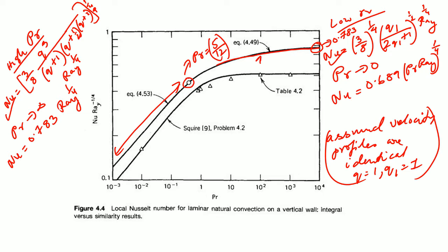Now, in this particular case, you can see that the Nusselt number to a certain extent depends on the analytical forms of the velocity and the temperature expressions, that there is some dependence. But when we choose a velocity profile or a temperature profile, there is always that trade off, and we will see how much that trade off is when we do our similarity solutions, because our similarity solutions will give you that kind of a profile. So, the similarity solution in itself has got that extra bit that it can predict the exact shape of the profiles, but this is also pretty reasonable from the two equations.